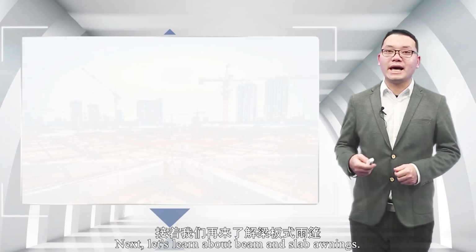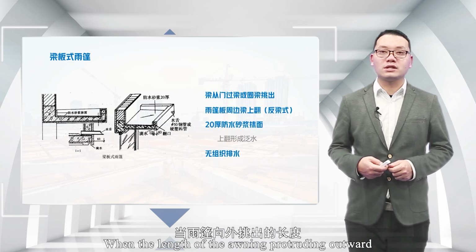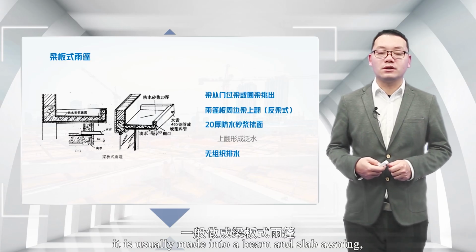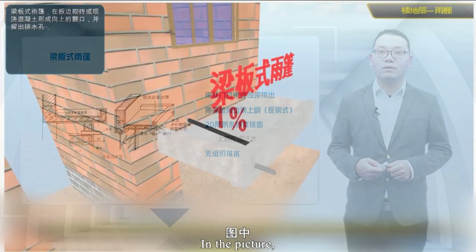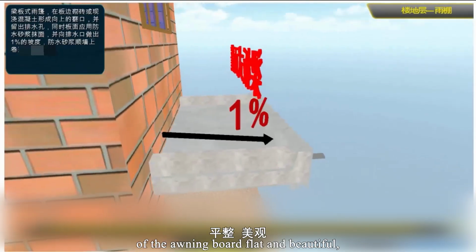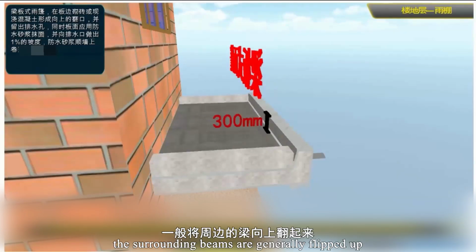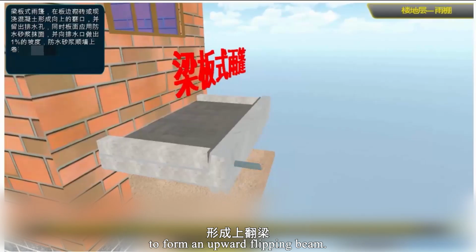Next, let's learn about beam-slab awnings. When the length of the awning protruding outward is relatively large, it is usually made into a beam-slab awning, with the beam extending from the lintel or ring beam. In the picture, in order to make the bottom surface of the awning slab flat and beautiful, and to prevent water dripping around it, the surrounding beams are generally flipped up to form an upturned beam.